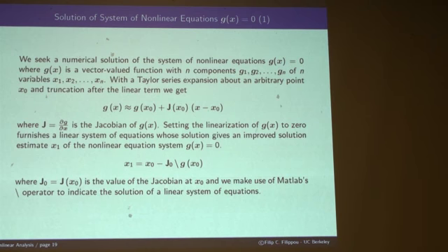Now, a key aspect of this process is the calculation of this Jacobian. All right? That Jacobian, calculating the tangent stiffness matrix and solving this linear system of equations over and over and over and over, can be an expensive proposition, particularly in multiprocessor environments. Because you have to formulate that matrix over and over and then bring it to some central place where you can basically solve for the equation system. Right?